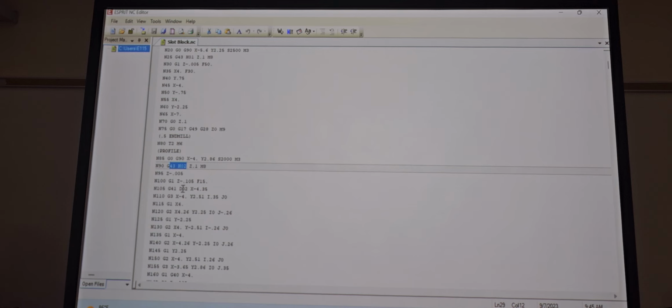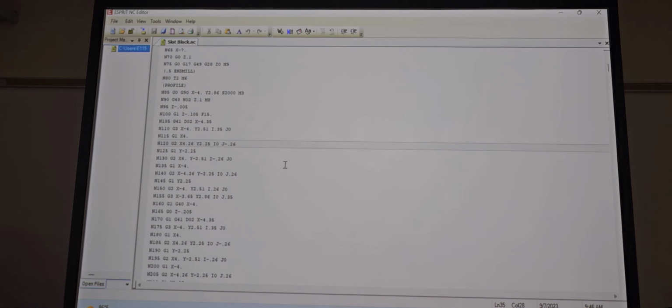And then over here, we pick up our tool number 2, right? G43, H02, G41, D02, right? If I would have left the other number at 5, like Antonio said, that would have said D05 on there. Now, when you put it on there, most of the time, do you run the graphics on there before you run? Oh, of course. Also, does it turn on the coolant? It says M8 turns on coolant. Yeah, because you can opt to leave that out or turn it on, whatever. But we got cooling in the machine now, so yeah, we're gonna leave it on there.